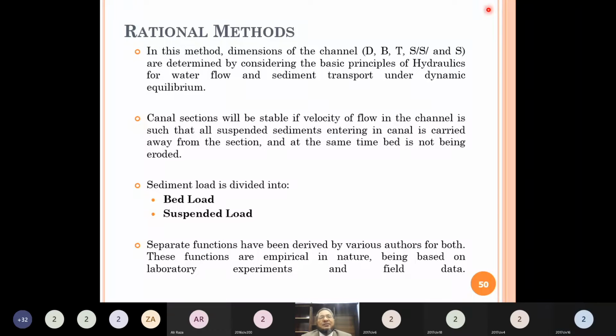So we being civil engineers, we have to design these channels: maybe the main canal, branch canal, then the distributary and minors. Please remember that we never take off these water courses from main canals and branch canals. We take outlets and water courses from distributaries and minors.